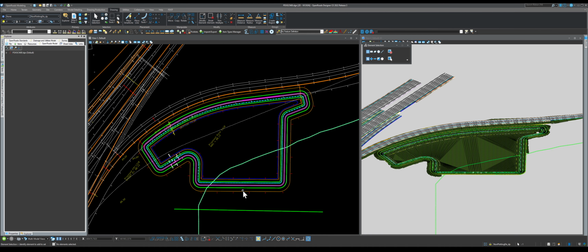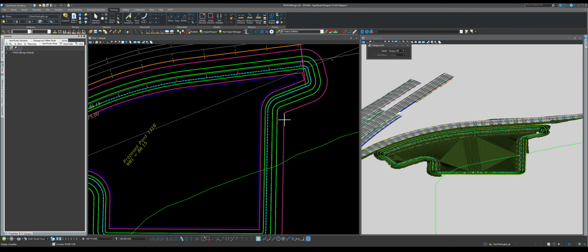The first thing here, you need to be 90 degrees perpendicular. First of all, let me turn off all these. Actually, I don't need them. I'm just going to hold right click, level off. I'm going to turn off all these ticks for the corridors, right? Because we don't need them. And all these extra things I don't need. And I know my roadway is here, so I don't even need to see it. Okay, so let's go place a line.